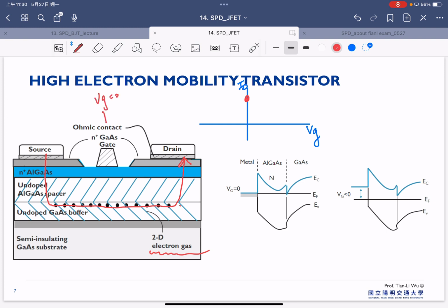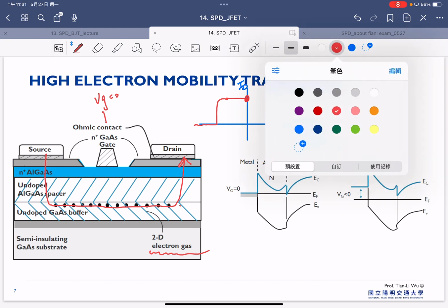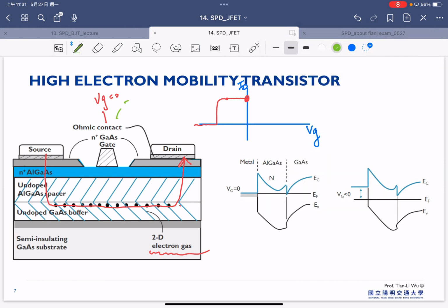Similarly to the MOSFET we have mentioned, this is exactly the case like the JFET. We just need to apply a negative gate bias until a certain moment where your threshold voltage is negative enough to have a larger depletion width. This is our depletion width.